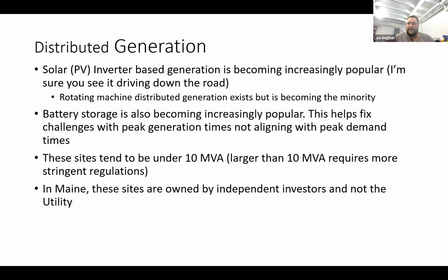And I think 5 to 6 o'clock is typically considered the peak demand time. Everybody gets home from work. Everyone turns on the stove. They might turn on the dryer. I think if you were to look at a load curve, 6 o'clock is usually the peak. So battery storage, they charge all day. They discharge when it's not sunny or windy, or whatever type of generation we don't have control over.